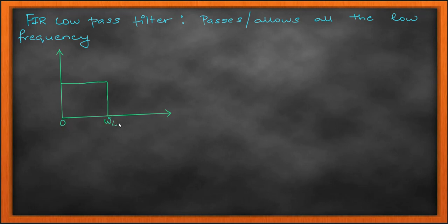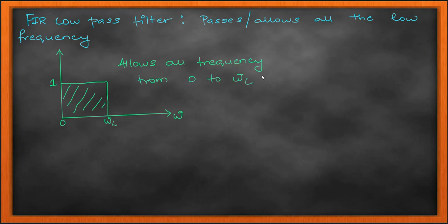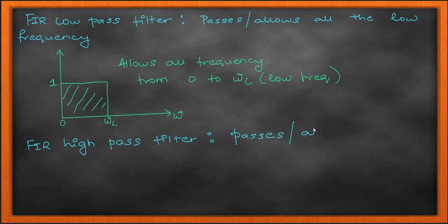So a low pass filter will help allow the audio signal to get through to your phone. What happens is when you speak and you have surrounding noise, suppose your fan is switched on, the sound from the fan is high frequency but your audio is comparatively in the low frequency range. So if I have an LPF filter in my device, the sound from the fan will get filtered because that is a high frequency sound.